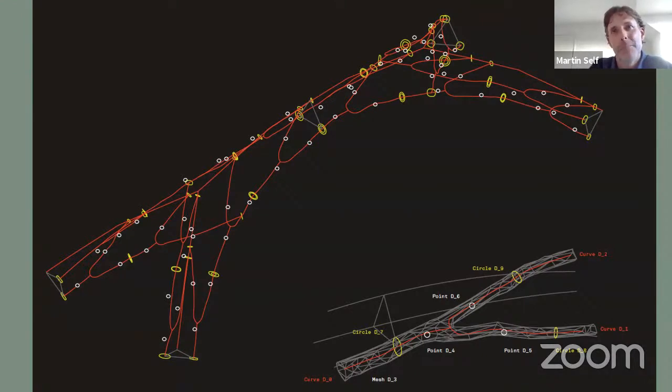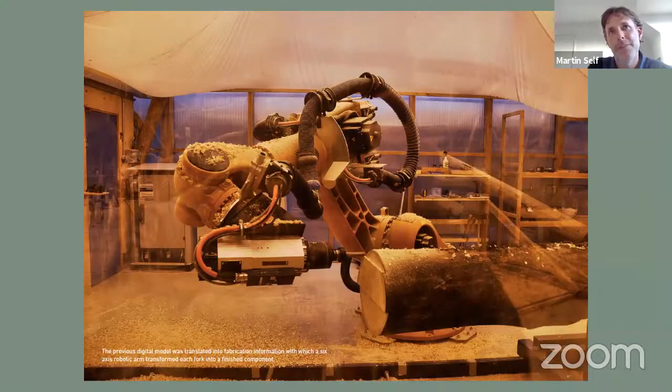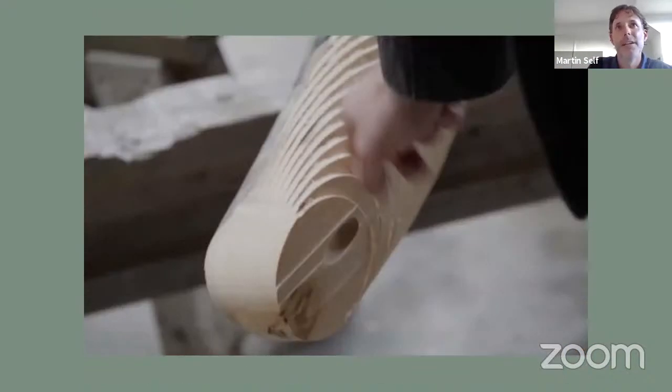So the pieces of wood just kind of butting along the compression axes of the truss. You know, so machining these flat faces in the ends of the pieces of wood where they bear on the neighbouring piece, adding some holes as pilots for the bolts that would go through and the shear plates and things like that. And this was a tenon of the connection where the branched tip would meet the top chord of the truss.